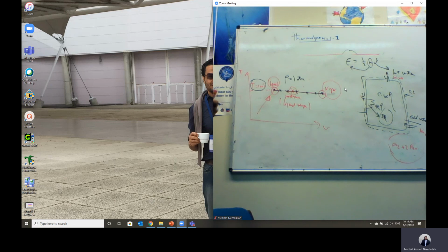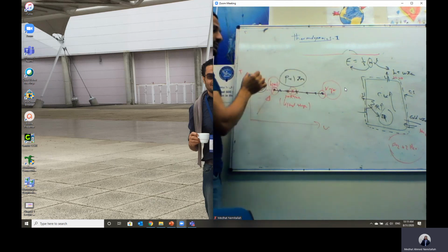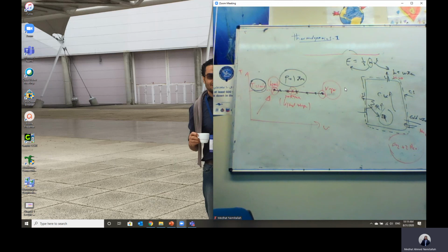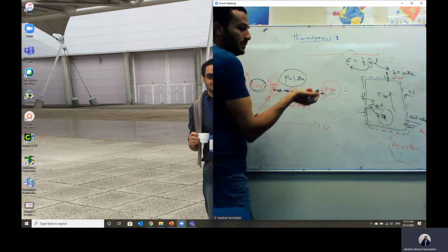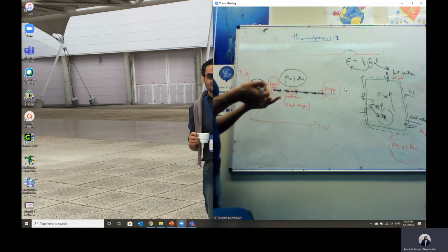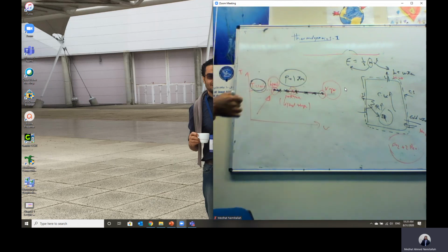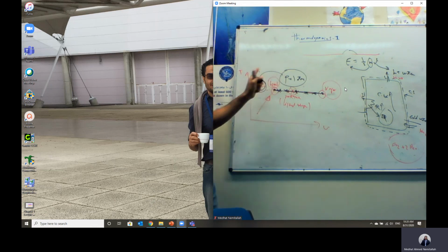The same temperature and also the same pressure, which is the atmospheric pressure. So if I say a liquid water, or a mixture of liquid plus water vapor, undergoes a phase change process, and the value of pressure is 1 atmosphere and the value of temperature is 100 degrees C, can we specify at which state we are? We cannot say, because all of these points have the same pressure and the same temperature. So in this case, pressure and temperature are not independent. Pressure and temperature are dependent.